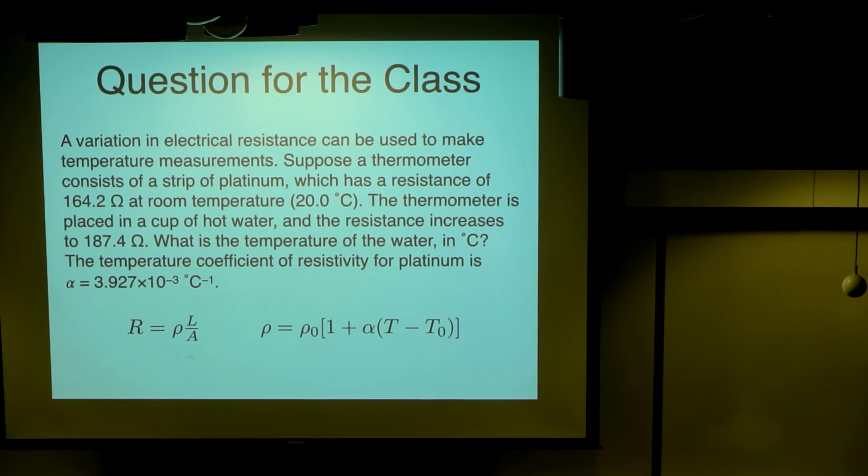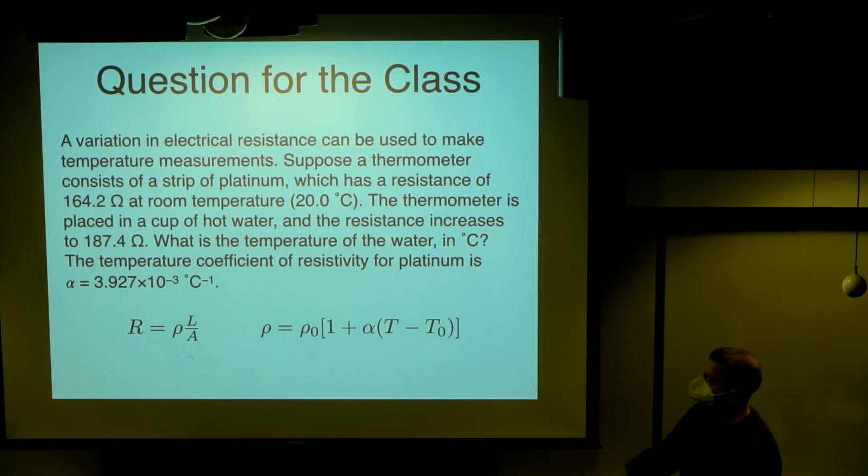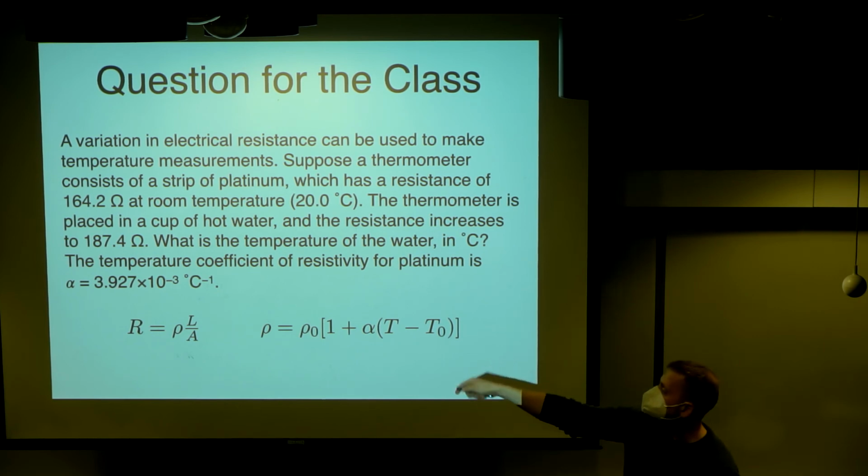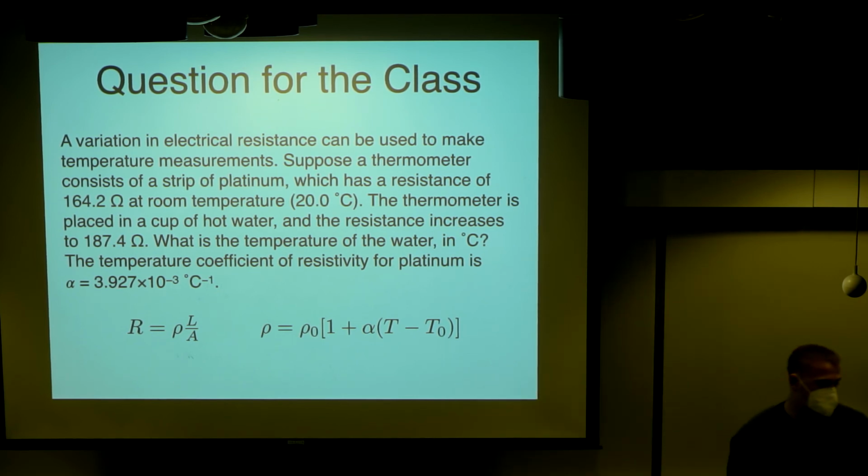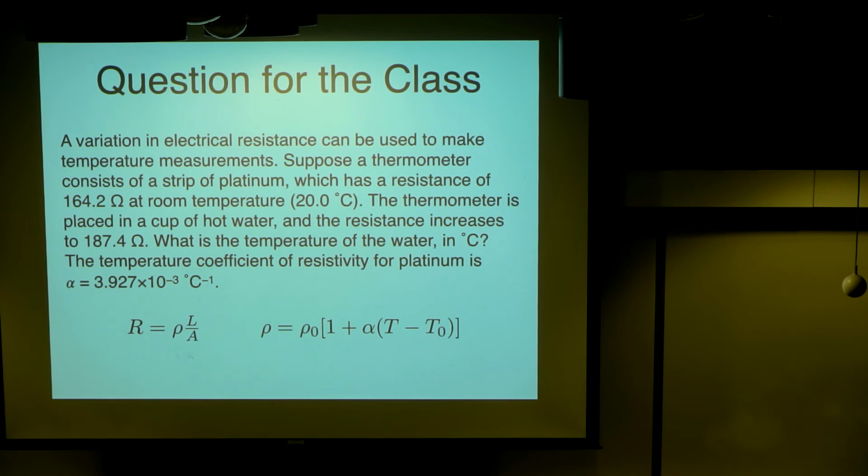So the question is, what is the temperature of the water? To do this, you're going to need the temperature coefficient alpha, which is 3.927 times 10 to the minus 3 inverse degrees Celsius.